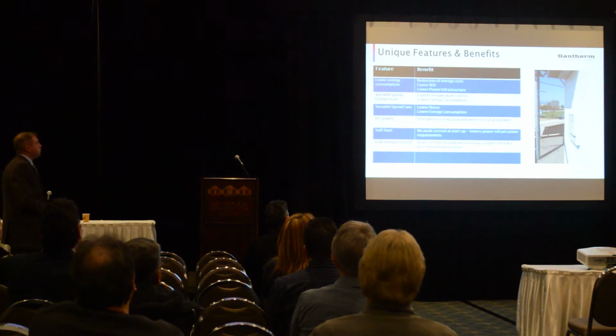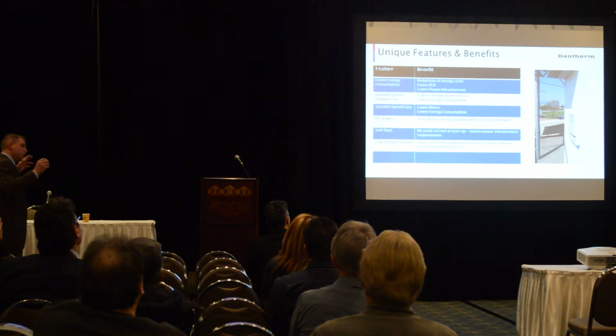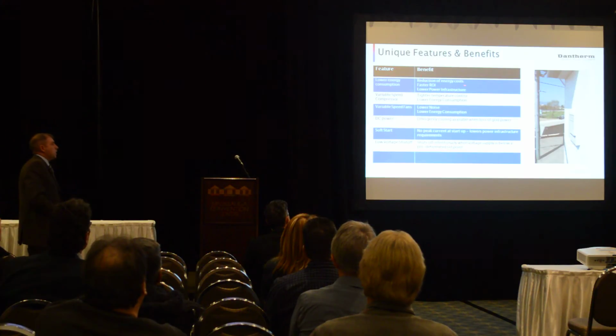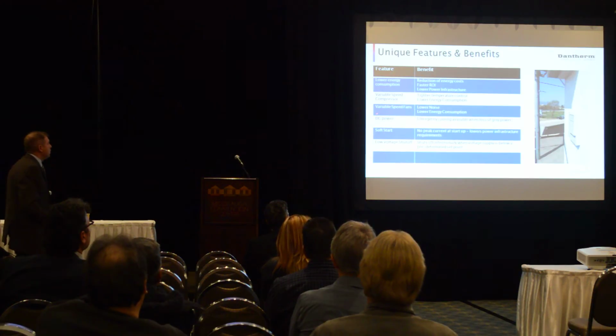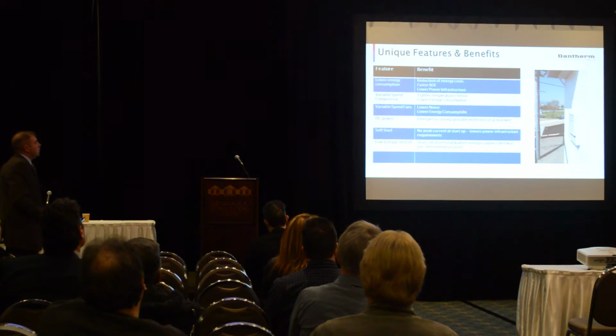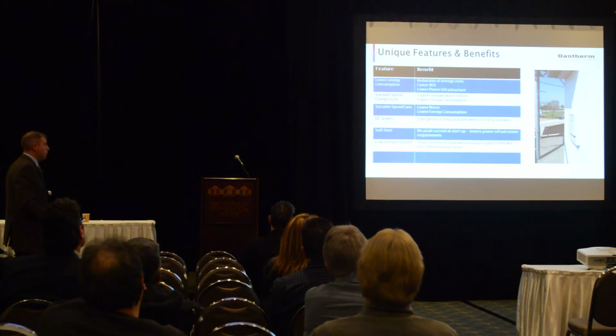So to recap, DC: precise cooling, variable speed to achieve your set point. You have lower energy consumption, reduction of energy costs, faster ROI, lower power infrastructure, variable speed compressor. You have that tighter temperature control like we saw on that last slide, that case study. Variable speed fans are also going to give you lower energy consumption as well as lower noise.